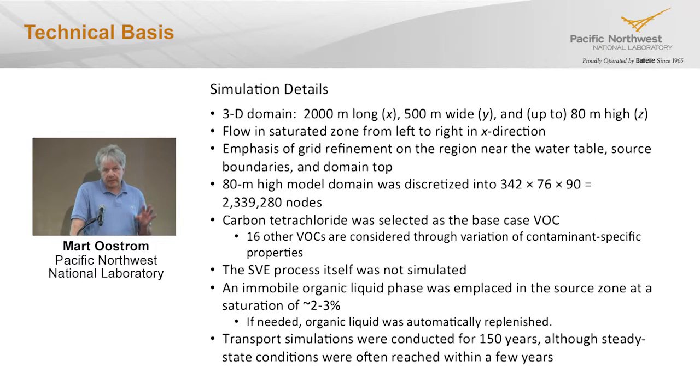It is important to realize that for this application, the SVE process is not simulated. We're looking at scenarios and conditions where, before you apply SVE or after you apply SVE, you have certain conditions in the field. So what's happening to the contaminant in your source zone? How is it being transported over time? The actual SVE process is not being simulated in this case, and that's the basis of your decisions. We're going to come up with systems that predict conservative concentrations for your decision making. So for these steady state simulations, we do not want the sources to deplete over time.